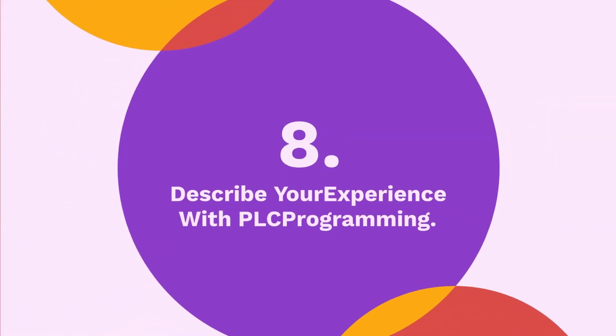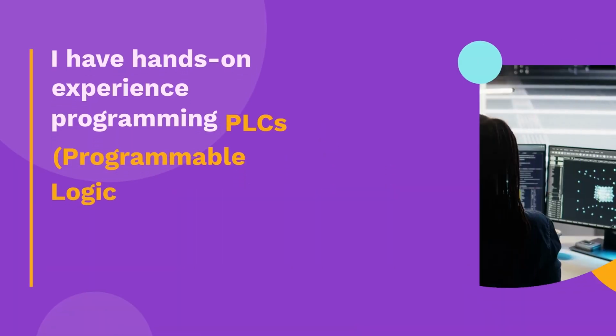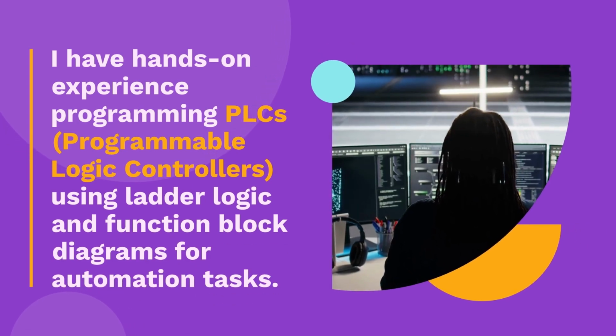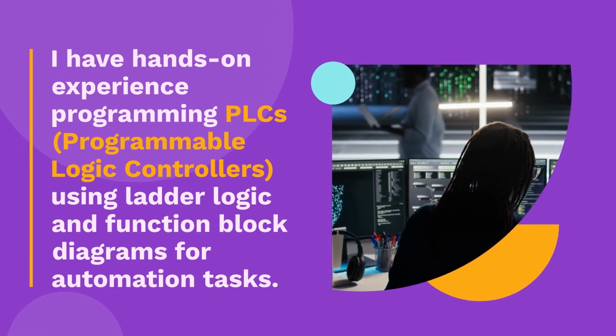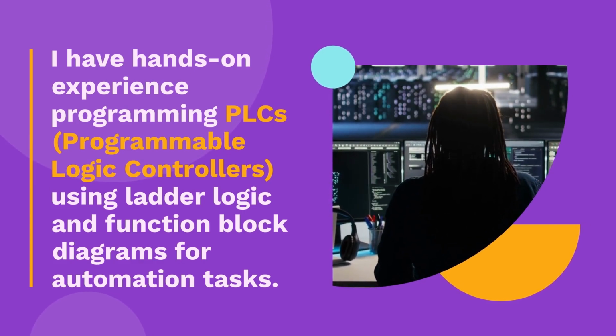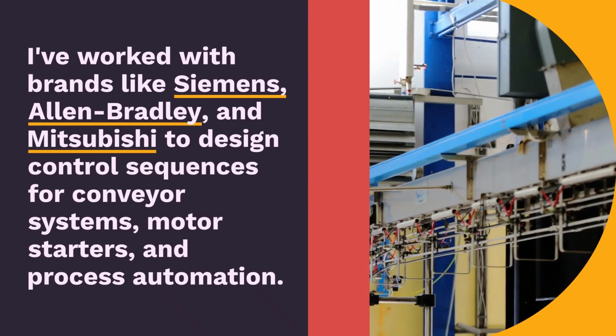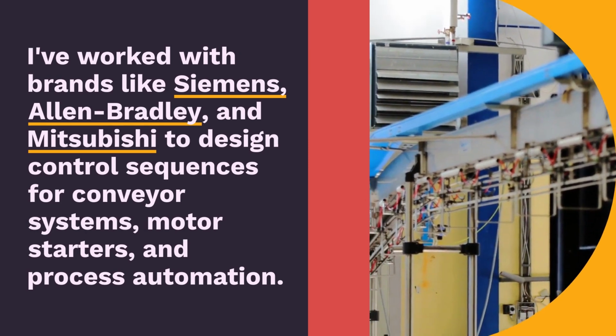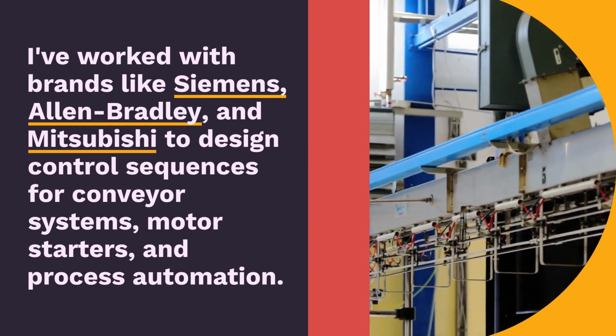8. Describe your experience with PLC programming. I have hands-on experience programming PLCs, programmable logic controllers, using ladder logic and function block diagrams for automation tasks. I've worked with brands like Siemens, Allen Bradley, and Mitsubishi to design control sequences for conveyor systems, motor starters, and